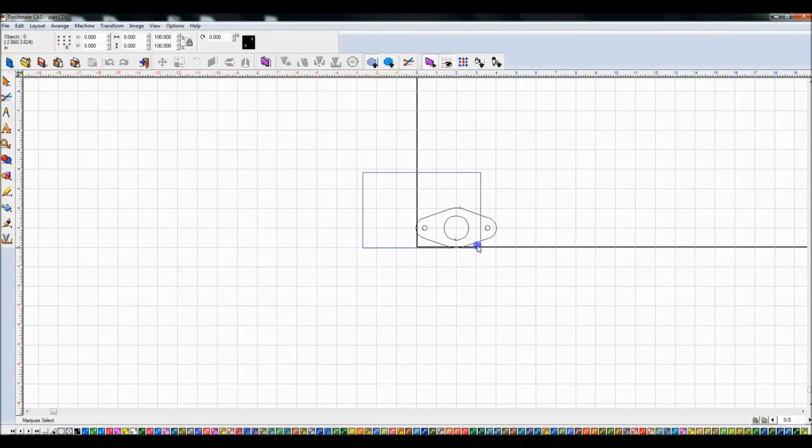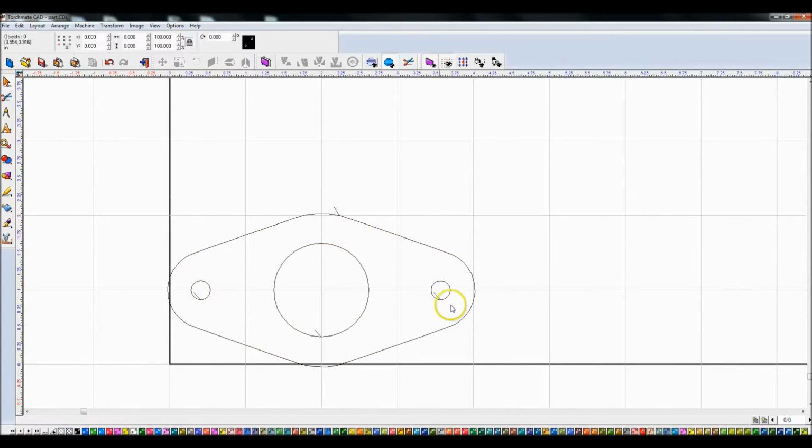Let's get rid of, click this button up here. Let's, one more time, show toolpaths. Get rid of the regular part, just show toolpaths. See what I mean? I don't have my lines coming in quite at a 90. I think it was 75 degrees or something. So this is a problem.